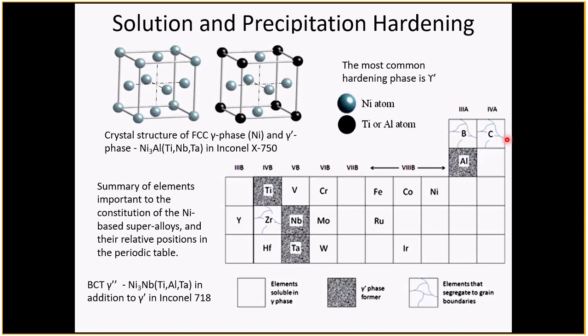neutron flux, neutron fluence, dose. It's been exposed to a certain amount of dose, and this has created so many displaced atoms. Blah blah blah." And they might attribute any changes they see to the neutrons, but ignoring the fact that it's been sat at temperature for 20 years. And the reason for that is that there's not much evidence or not much data available where somebody's taken some of these alloys, Inconel X750 as an example, or just any alloy, and actually sat it for 20 years at the same temperature you have in a nuclear reactor.